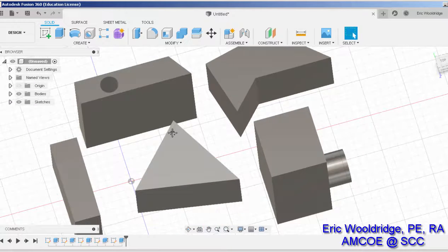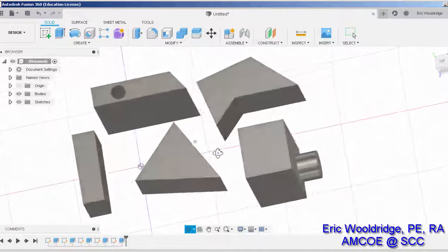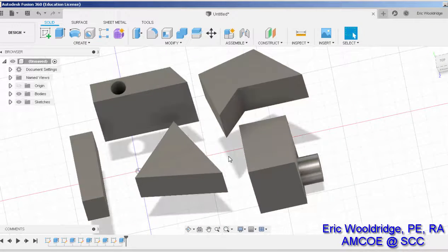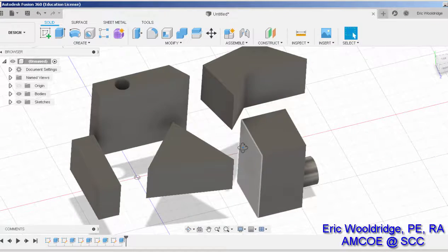Alright, so that's a good little exercise. You've done several sketches and several extrusions. It honestly can be that simple. We'll do more advanced stuff as we move along, but in this little episode you've created some structures in 3D. You're learning to use the roller button on your mouse. You're learning to hold down the roller button on your mouse and hold down the shift key to get an orbit. And you've gone from the sketch menu to drawing and also creating extrusions after you're done sketching.